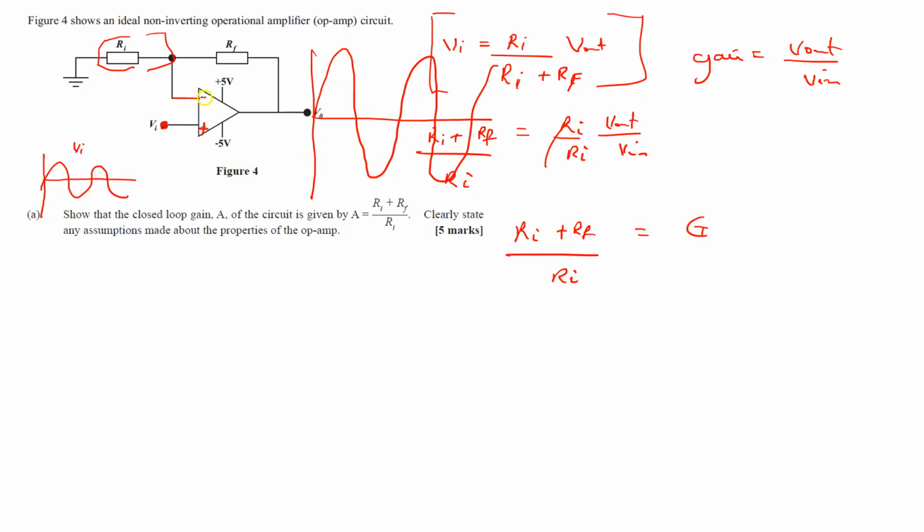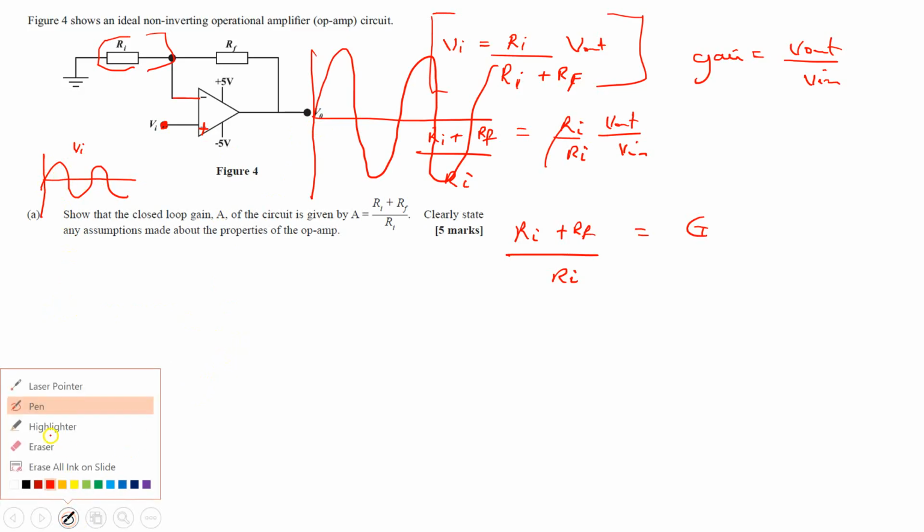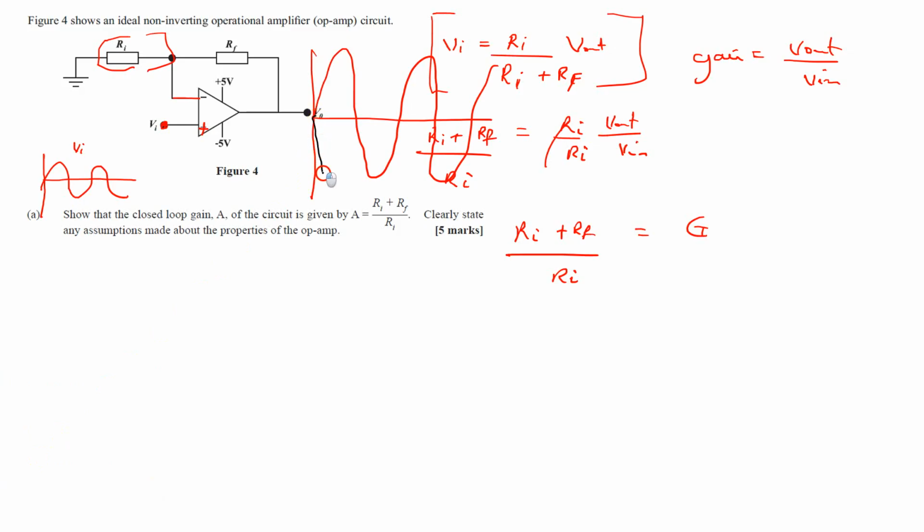However, if we're talking about the inverting operational amplifier, what that means is that if my signal was positive at first, then it is now going to be in the opposite portion. So I would expect that the amplified output signal would look the opposite, right? That's what we mean when we say you're taking the input and inverting it, as the name suggests: you have the inverting terminal, and you have the non-inverting one. All right.